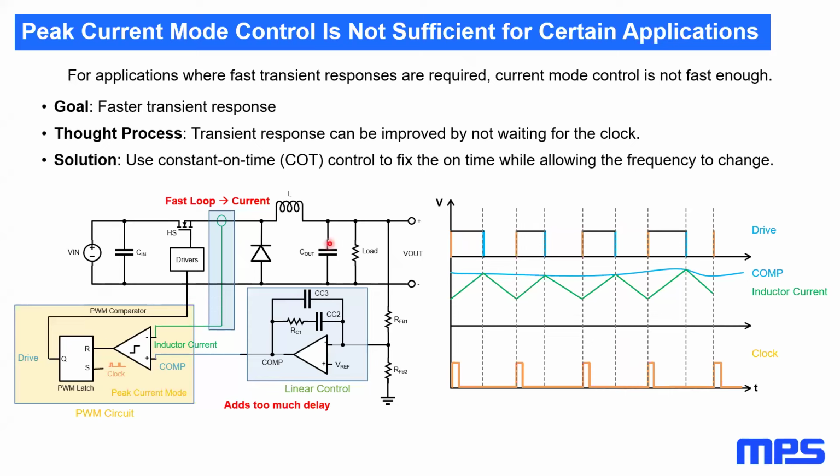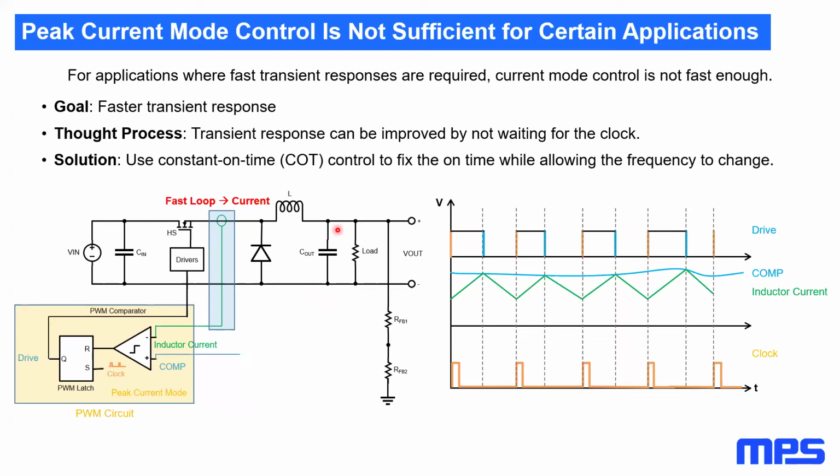So if we want to increase speed, then the first thing that we can do is we can just scrap our compensator and directly connect the output voltage sensing to our comparator. In this way, we can eliminate this delay. And in the second aspect, I'll go into that later on, but of course, without the compensator, we don't have this compensation signal that we were seeing here. So we substitute this for a fixed voltage reference.